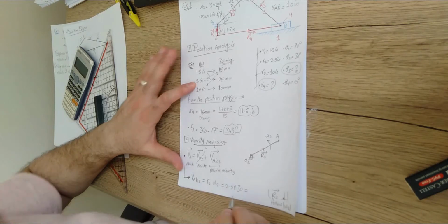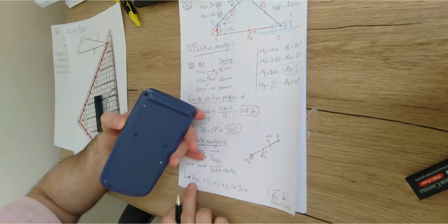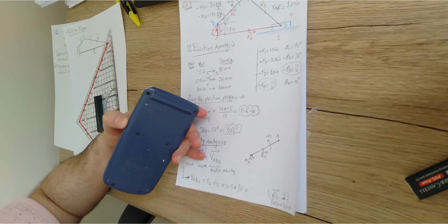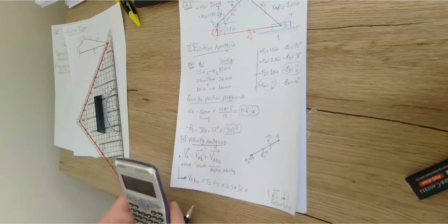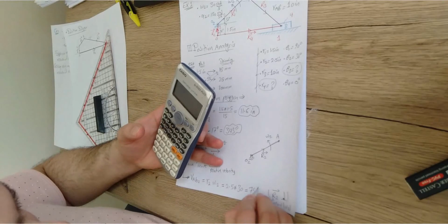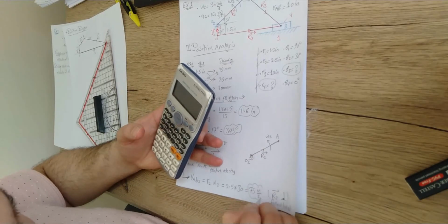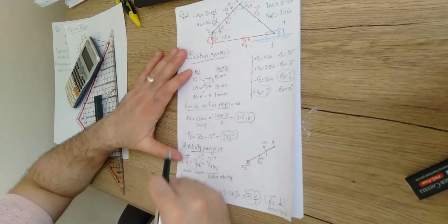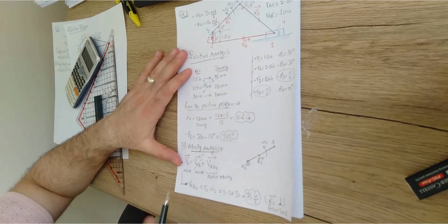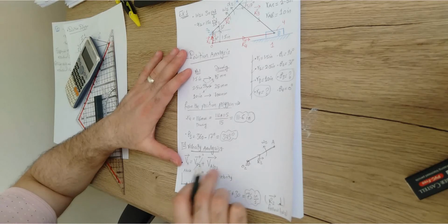If you do the calculation, this is going to give us a value. This is the value of the velocity vector. This is the direction of the velocity vector: it should be perpendicular to R2 and follow the rotation of omega 2. Make sense? So 2.5 times 30 gives us 75 inches per second. This is the velocity for this length. Make sense? So this is the first link and this is the plan. I put a plan here, right? This is the equation. The thing that we will be drawing is this, VA relative to O2.